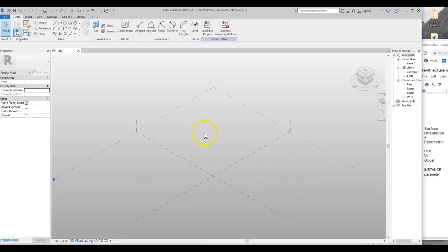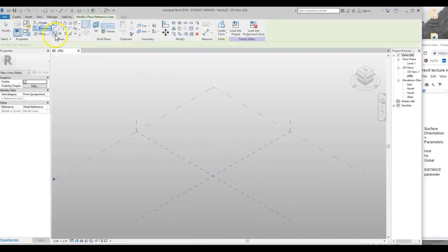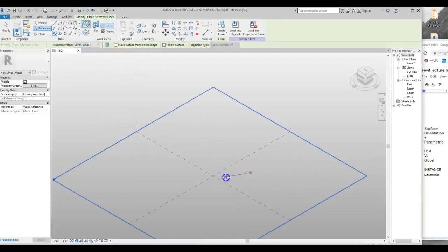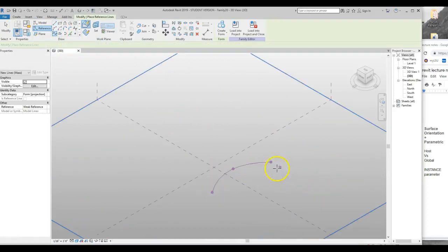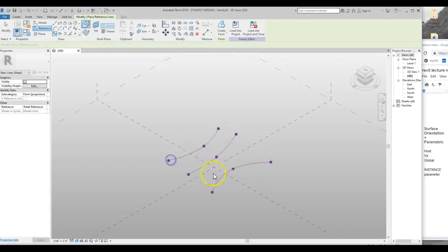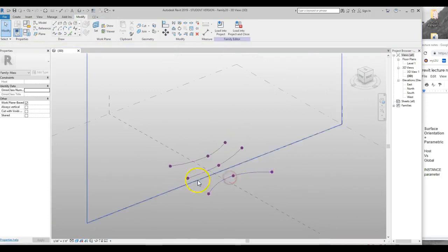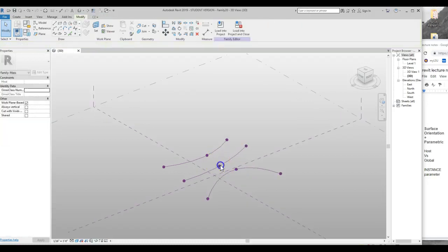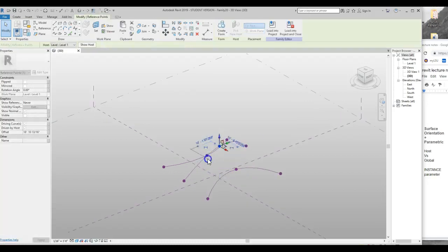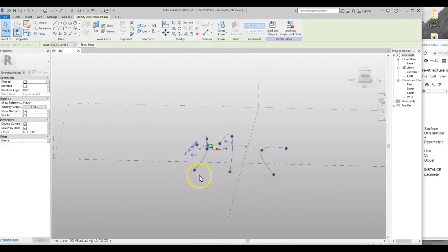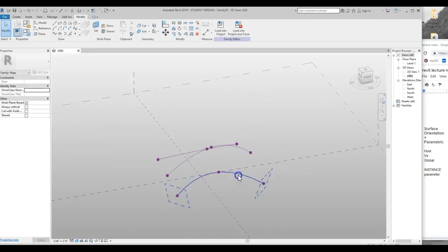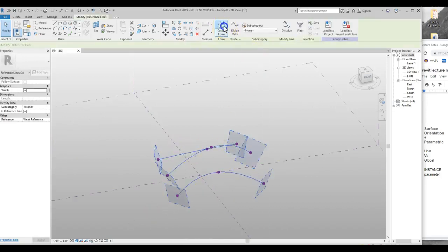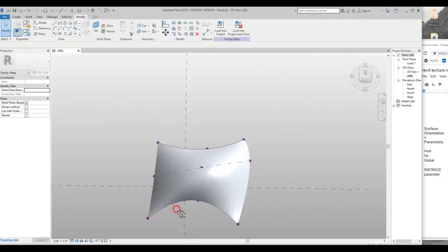And I'm going to give a little tip that when you're doing your reference lines and drawing these first surfaces, drawing from right to left, this seems weird each time. I do them all right to left. Makes the surface face up. That sounds a little funny, but what I'm doing here is I'm just grabbing these and making sure they're all not flat. Okay. They're all reference lines. I can grab all three of them. Make surface, and now we have this complex form, right?